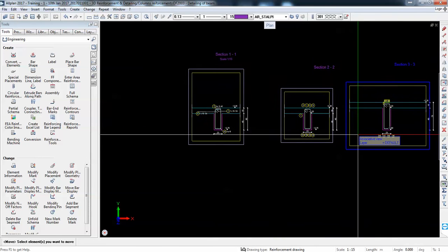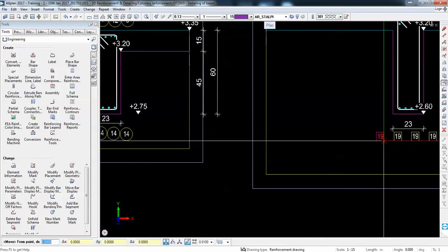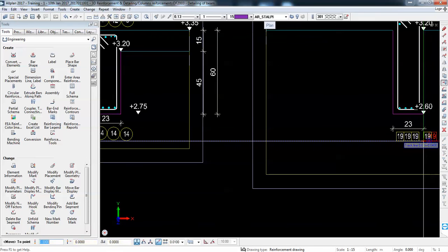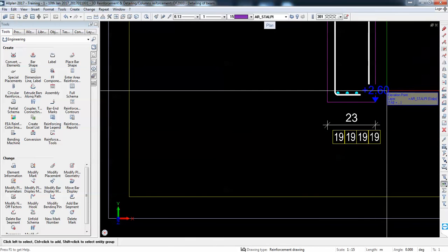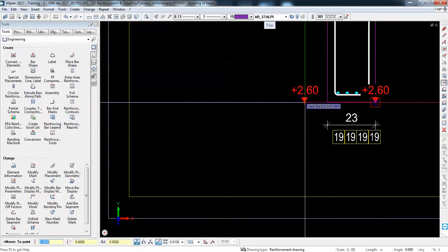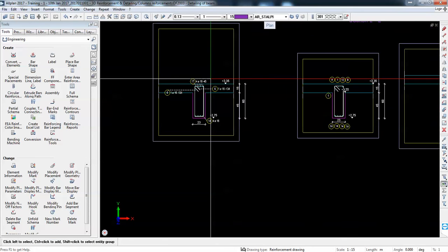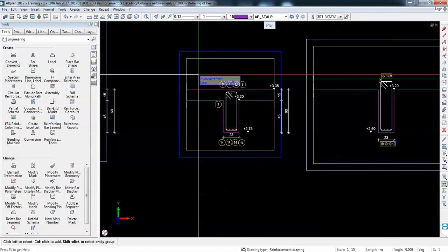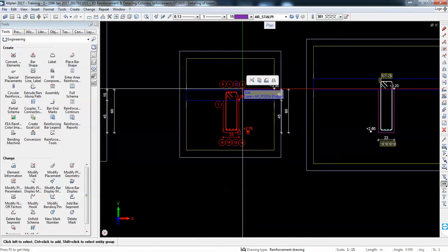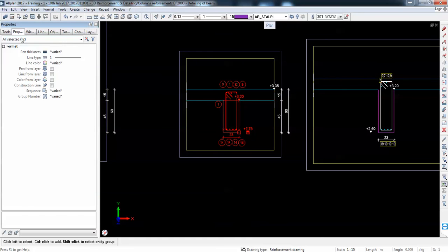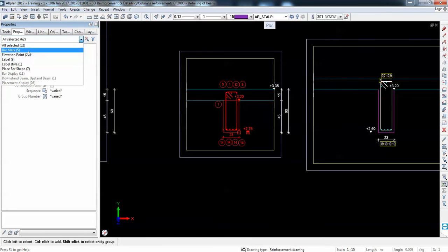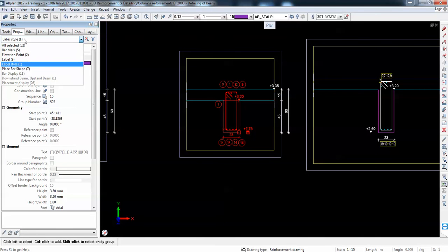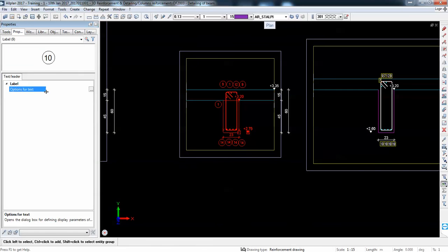The problem is now, as I mentioned, if I do any change in the detailing way or standard, it will not affect what I already did. So my work is not affected, and in case I want it to be affected, I have to do a small trick. So in order to replace these with rectangles, so already done work, I have to select it, go to properties, and here it's about labels. Not this label. No, label should be. I have to do a change for it.